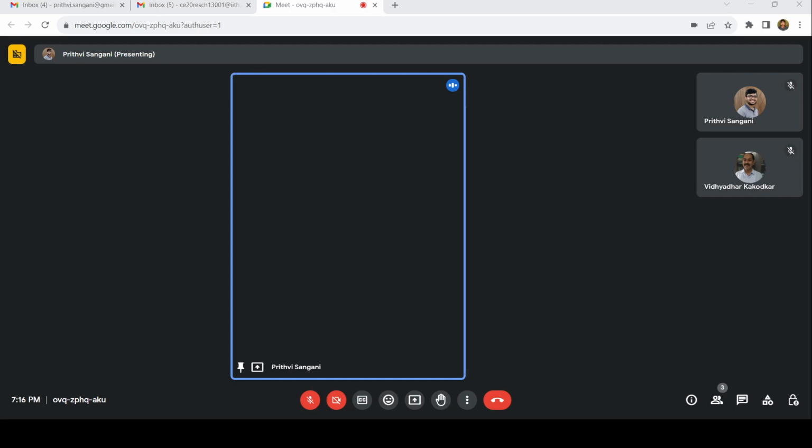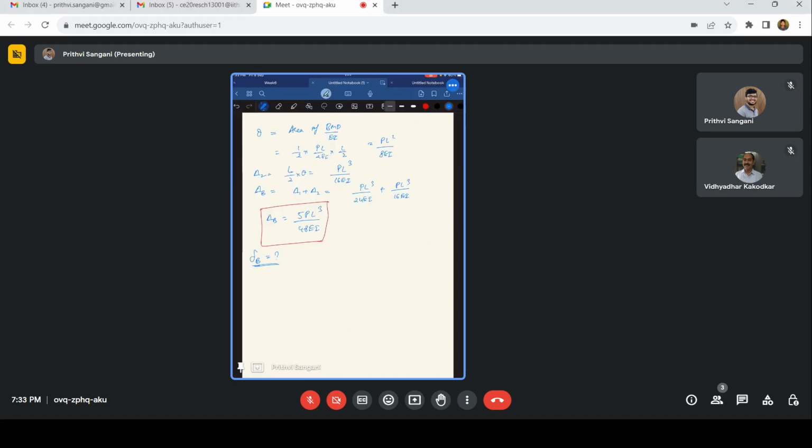For this, we can have again the same cantilever beam, and then we apply the force VB. So we have a deformation profile, a deflection profile, something like this. So this is delta B. This is L. So what are my reactions? So in this direction, it has to be, yeah, this is VB times L, and this will be downwards. How much? VB.